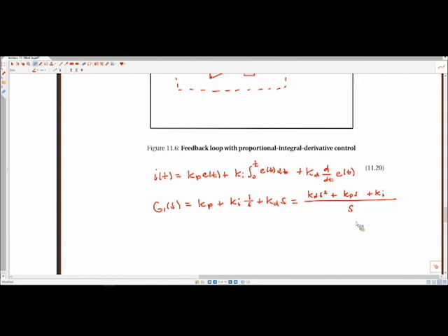So keep in mind the units on all these are different too, so the magnitude of the term is a little bit fictitious. If we go back here, if I is in current, it depends on what your input is. I is in current, and an error would be, in this case, meters. That means the units on Kp have to be amps per meter. If we do the integral of error, that's E dt, so this is meter seconds, which means Ki has to be amps per meter second.